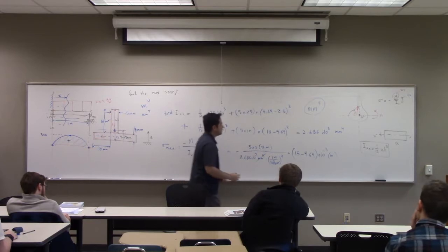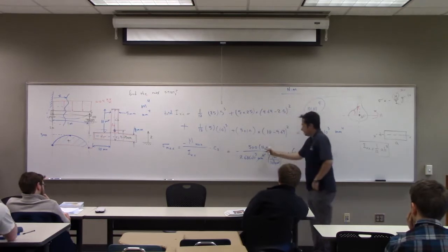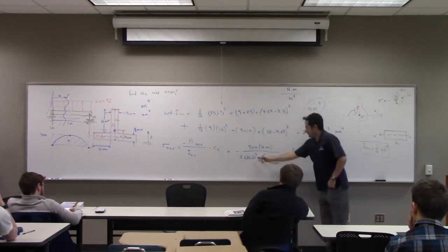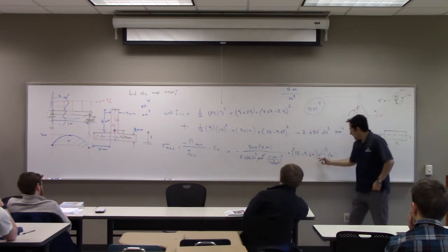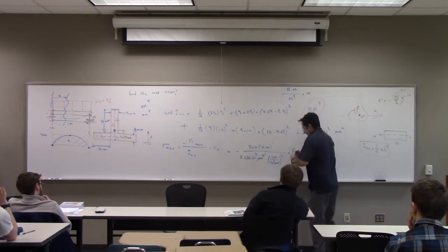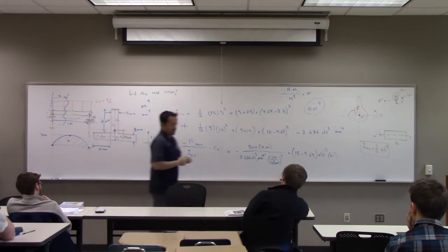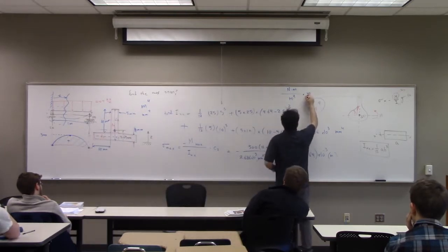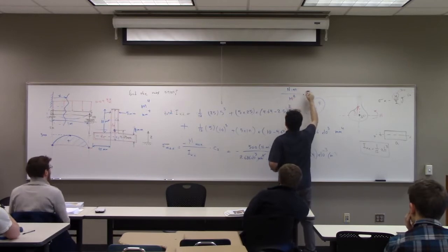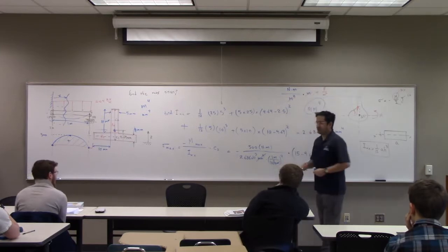So let's write the dimensions. Here, you have Newton meter on the top. The bottom, you have meter to the fourth power coming from this resultant thing. And then right here, you have a meter times a meter. What do I get? Newtons per meter squared. So this is meter squared with meter to the fourth power. The end result is Newton per meter squared.